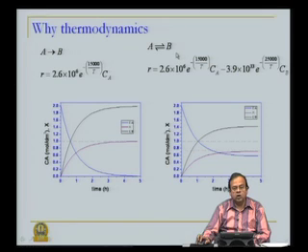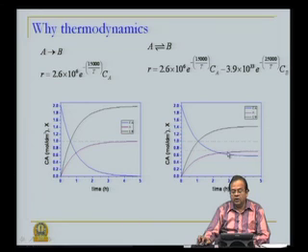Thermodynamics tells us a lot about equilibrium, and hence we need to know at what conditions such saturation will occur. Now, operationally this is important, because for example, if you have designed your reactor to run for 3 hours, you are getting a certain conversion. Now, it is natural to expect that if you run this reaction for a longer time, you will get a little better, but that is not what is happening over here. Whether it is 3 hours or 4 hours or 5 hours, practically the conversion is the same. So, any investment that you do in running this reactor for a longer period, such as 4 hours or 5 hours in this particular case, is not going to give you any additional returns. That means it is not a wise thing to do.